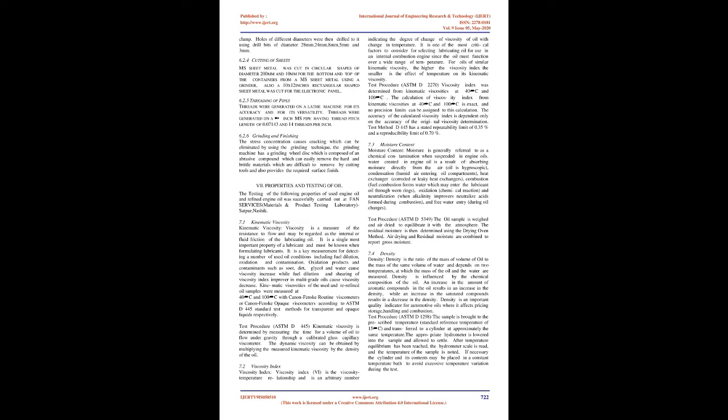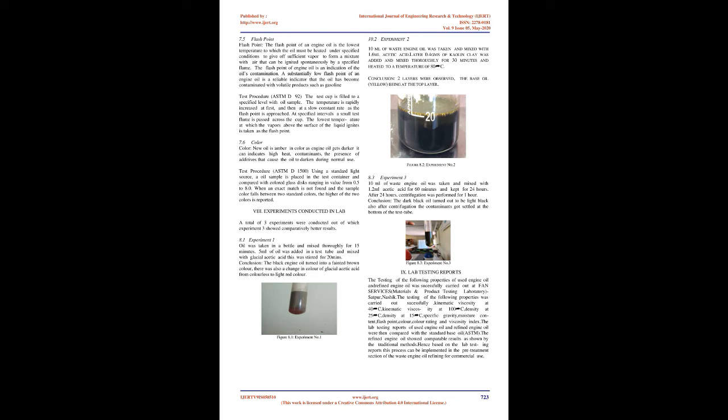Test procedure: ASTM D2270, viscosity index was determined from kinematic viscosities at 40°C and 100°C. The calculation of viscosity index from kinematic viscosities at 40°C and 100°C is exact, and no precision limits can be assigned to this calculation. The accuracy of the calculated viscosity index is dependent only on the accuracy of the original viscosity determination. Test method D445 has a stated repeatability limit of 0.35% and a reproducibility limit of 0.70%.